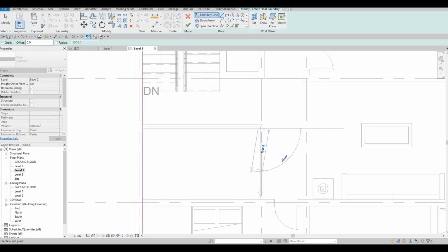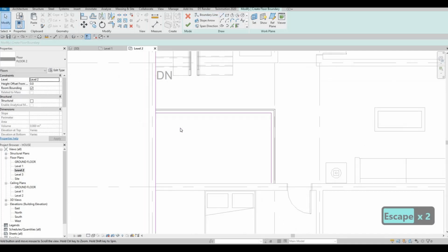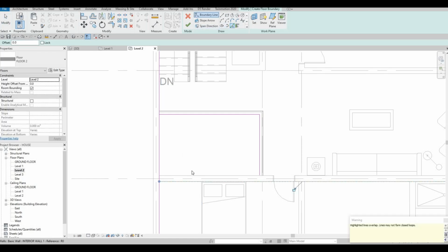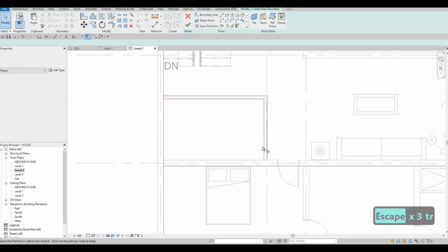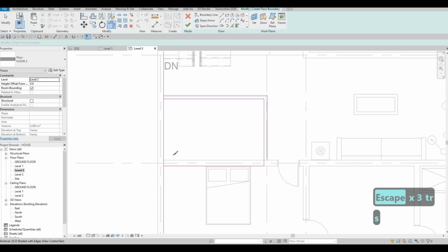Of course, there should be gap between the railing and between here. And then now, what I'm gonna do is I'm going to pick this line actually, and then let's trim and extend here, and then SL here to slice it up, and then trim and extend right here as well.